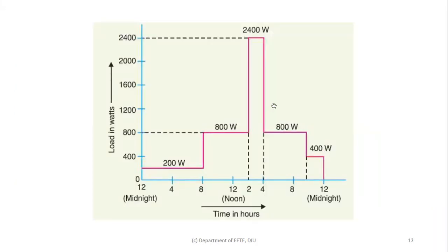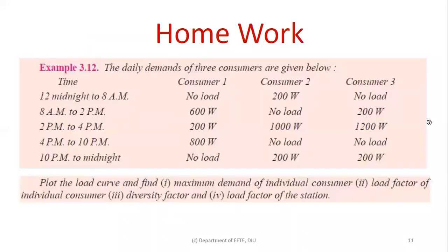So you will build the load curve using that. And the maximum value will be the maximum demand, that is 2400 watt. 2400 watt is the maximum demand from this load curve. So you will find out the maximum demand. Okay.